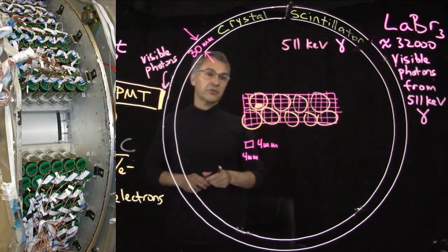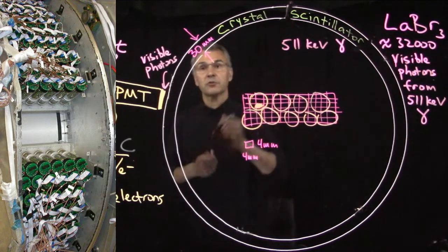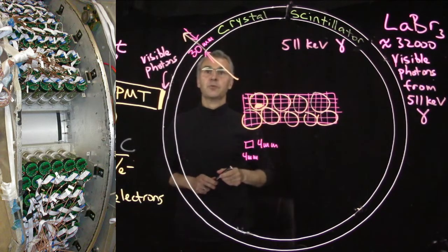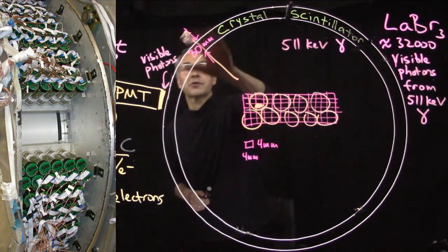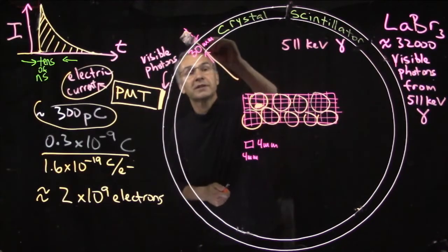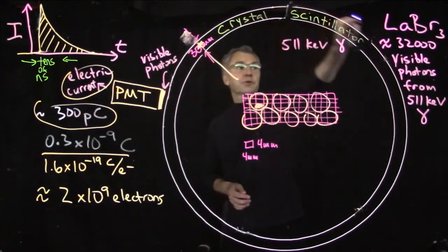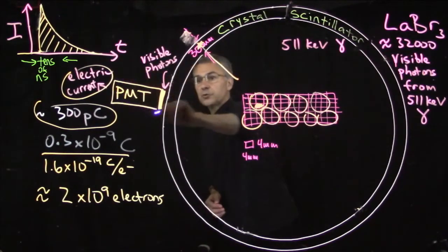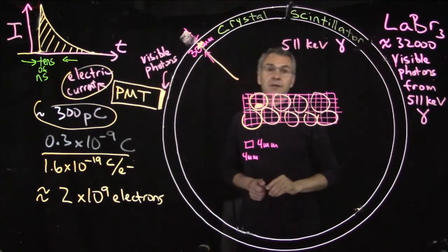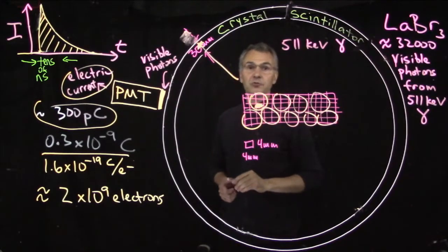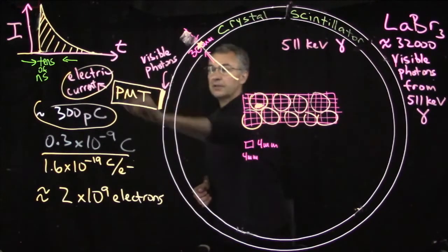And when you figure out which scintillating crystal was hit, you can figure out where the X-ray photon went. It doesn't actually pass all the way through. It gets partway through and then undergoes a photoelectric interaction. So then around the circumference we have 432 of these photomultiplier tubes, and that means we need a system of electronics to read out 432 electrical currents.